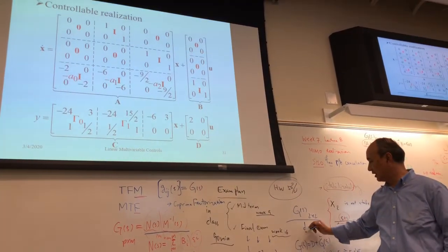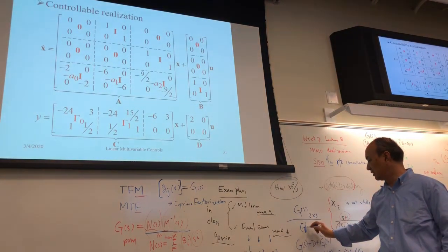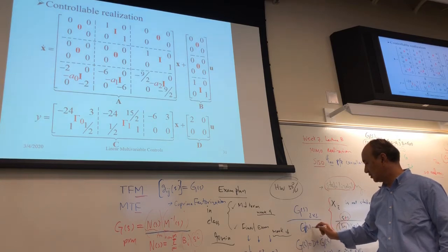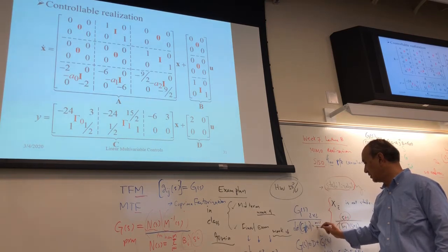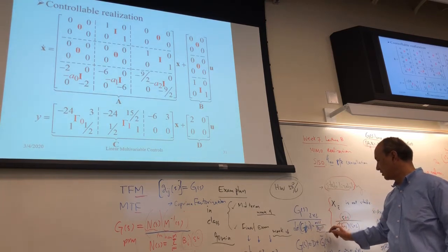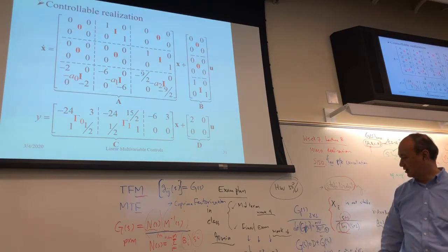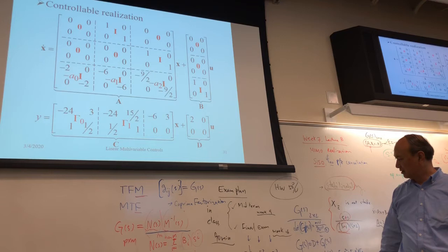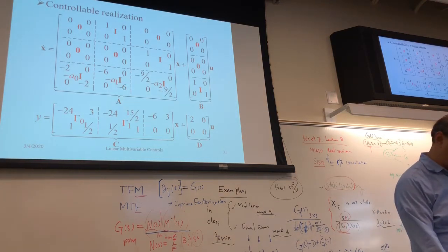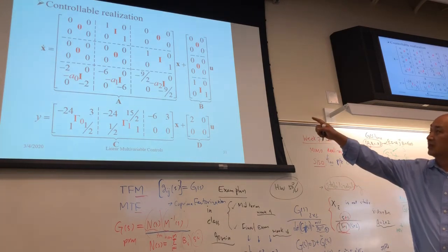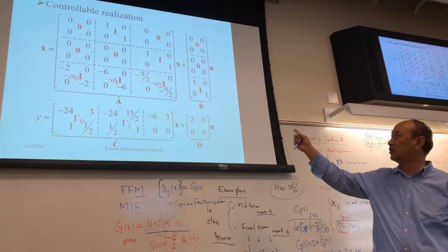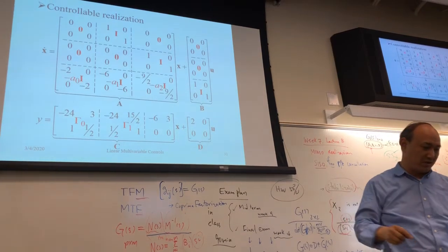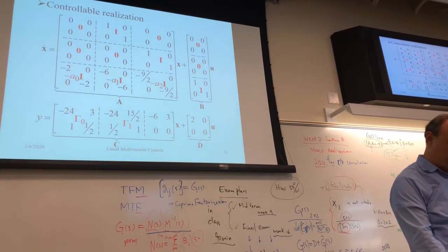But DG, we have seen the DG. The determinant polynomial, the denominator here, is N(s) divided by DG(s). So this DG(s) is third order, okay? Third order. But in the end, the system ended up with 6 by 6, 6 by 2. So this is 6 and 2 inputs. We wanted to accommodate 2 inputs. We expanded our internal state to 6 instead of 3.